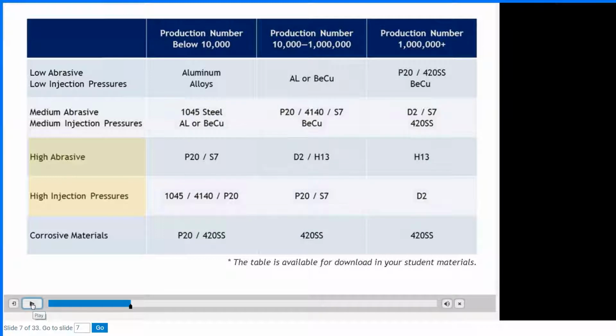As always, it's all about the cost economics of using mold steel. Some of them are more expensive, as you know, and harder to machine and more difficult to treat. For example, beryllium copper, or many of you may know Mold Max HH, high strength alloys. Those are good for certain applications where we need a high thermal conductivity, but they're more expensive. So we will see later in this lesson an example.